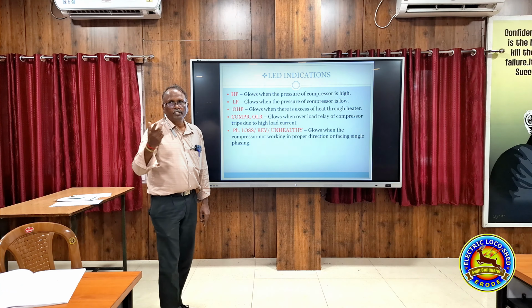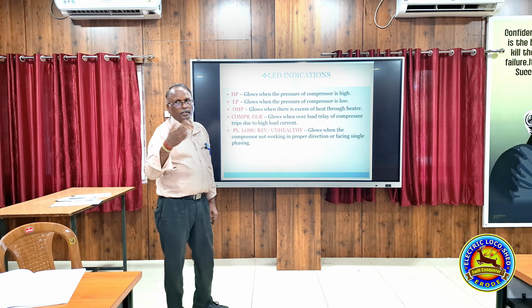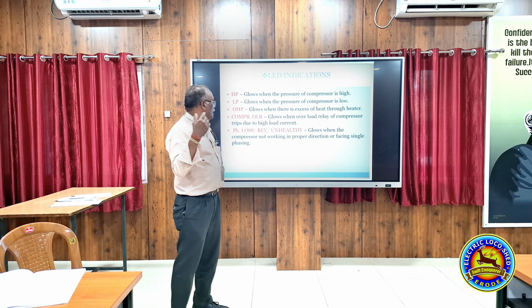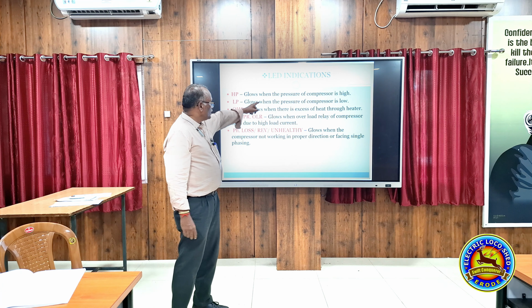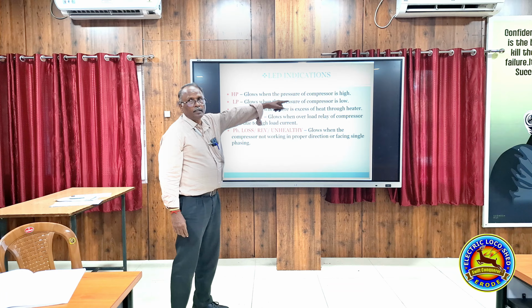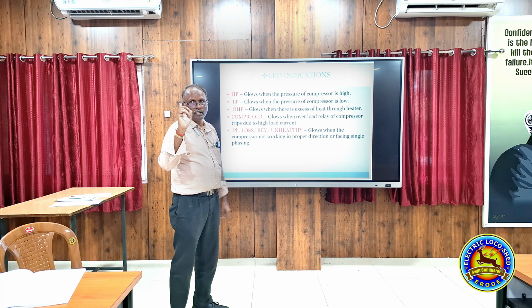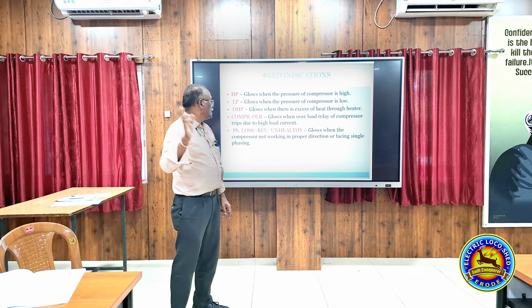HP indication: when the pressure goes high, the HP indication will be there and it will glow on the trip. HP glows when the pressure of the compressor is high. If the compressor is abnormal or any high pressure is there, then it will trip.